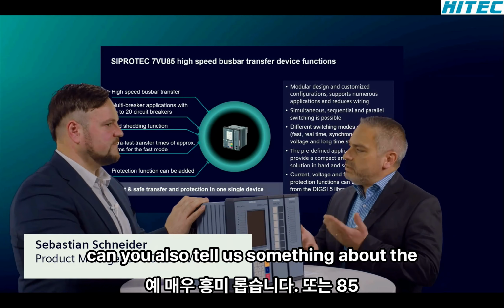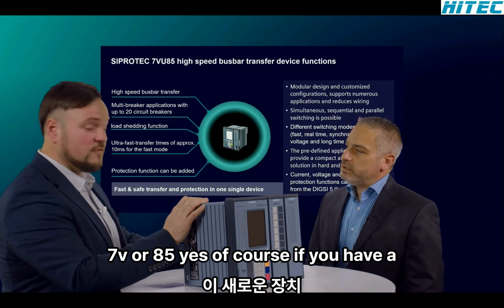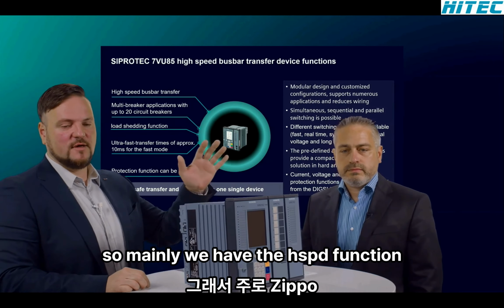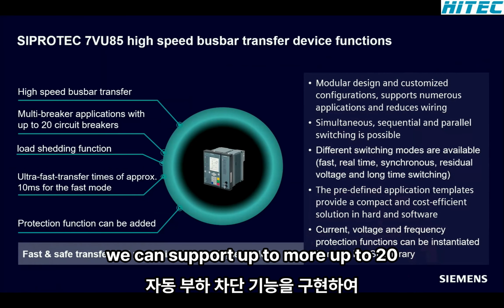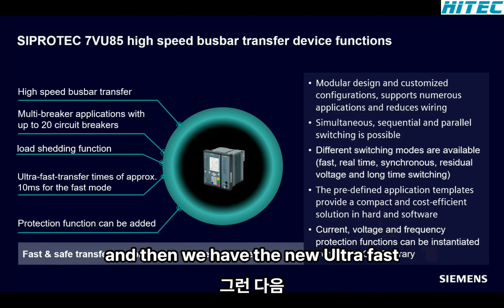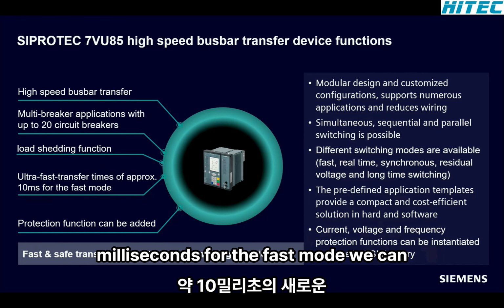But can you also tell us something about the functions and the highlights of the new 7VU85? Yes, of course. If you have a look here on the slides, you can see the device functions of this new device type. Mainly we have the HSBT function implemented on the CIPROTEC 5 platform. We can support up to 20 circuit breakers. We have the automatic load shedding functionality implemented. And then we have the new ultra-fast transfer times of approximately 10 milliseconds for the fast mode.